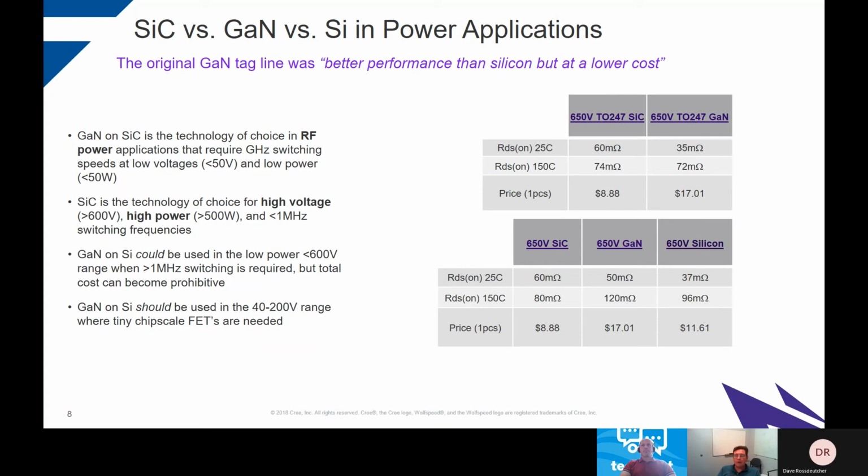So if you correlate to the right RDS(on) piece of silicon carbide versus silicon or GaN, in our case, let's go back to that 60 milliohm datasheet, which is 80 odd milliohms hot. That equals the performance of a 50 milliohm piece of GaN or a 40 milliohm piece of silicon. And when you look at the sticker prices lined up, and I show you some examples here, component to component, actually the silicon carbide MOSFET is the lower, more cost-effective product.